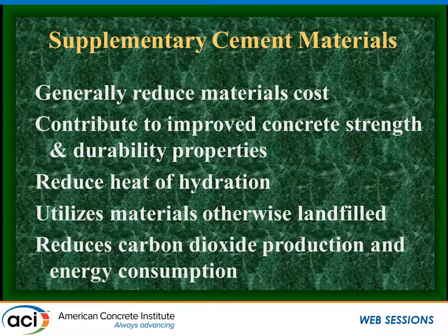Now, the supplementary cement materials that we're using, why are we using them? Well, it started with, this is something that can reduce our materials cost. We found this was a replacement for Portland cement. Fly ashes, back when they were introduced into concrete, were typically a fourth to a third of the cost of Portland cement, and we could use that and get some comparable strengths and performance out of it. That was the origination of the process.